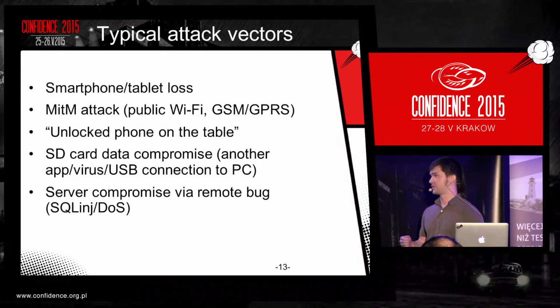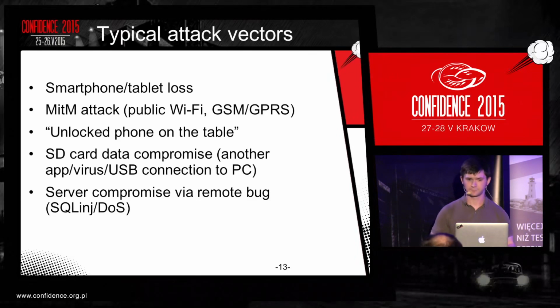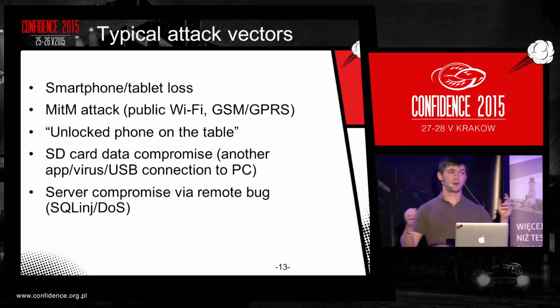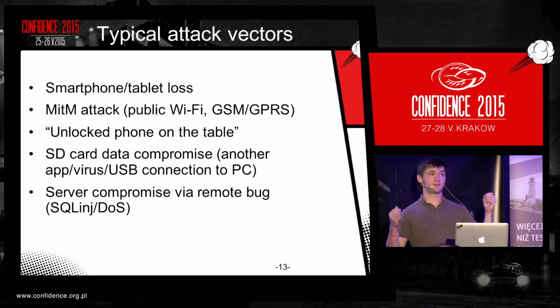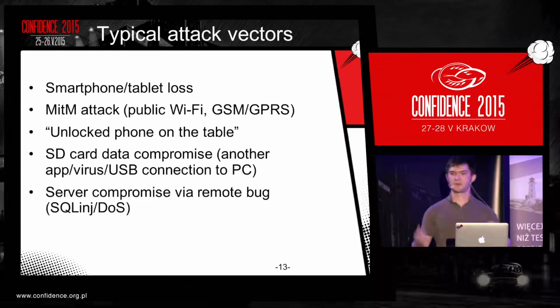Also, some applications store their data on SD cards. This data can be HMI project files, configuration files, logs, or other sensitive information. So some virus or another application that has access to the SD card can modify this information. For example, it can disable all buttons in the HMI project file. So when the operator tries to do some actions using his mobile application, for example, tries to switch off some device, he will have no luck.